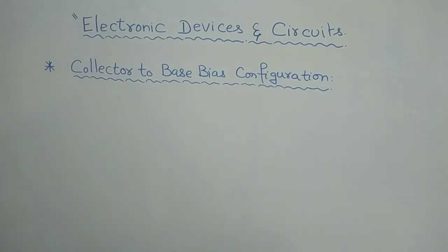We are discussing the transistor bias configurations, right? In the last presentation, if you recall, we saw one of the simplest and foremost important biases of a transistor, the fixed bias. We saw the circuit diagram, how simple it is, and we saw how stable that fixed bias circuit is by evaluating the stability factor of that particular circuit.